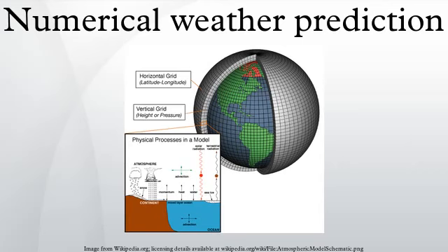Ocean surface modeling: The transfer of energy between the wind blowing over the surface of an ocean and the ocean's upper layer is an important element in wave dynamics. The spectral wave transport equation is used to describe the change in wave spectrum over changing topography. It simulates wave generation, wave movement, wave shoaling, refraction, energy transfer between waves, and wave dissipation.